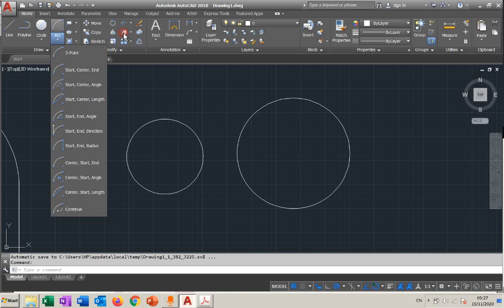Fillet is one of them that we will use. They call it tan arc. I suppose tan radius arc indeed, because there is radius as well. Tan radius arc is not within here. Two tangents, a radius and an arc is not there. So tan radius, we don't have it within the arc command. But remember, fillet can be used.